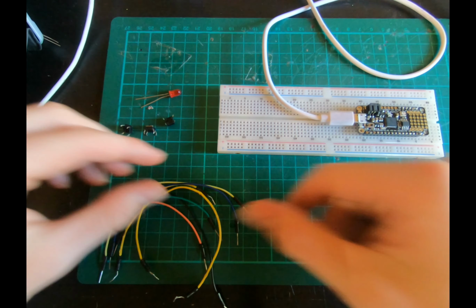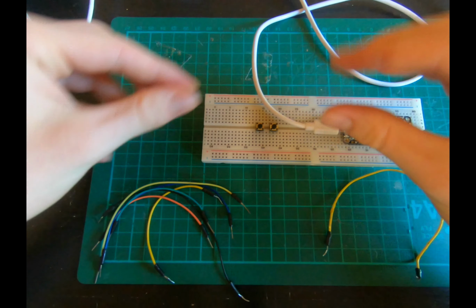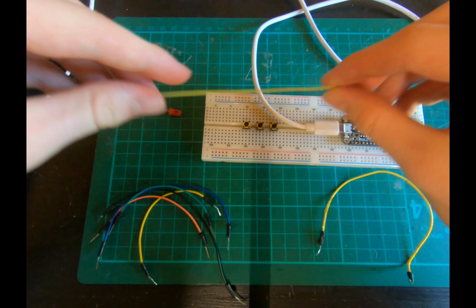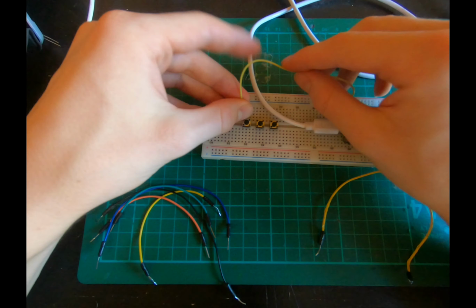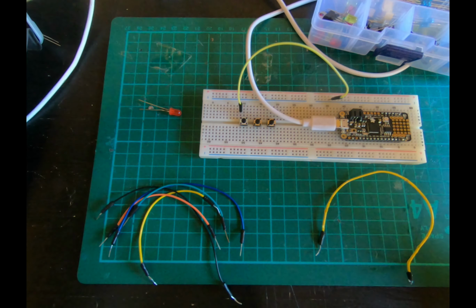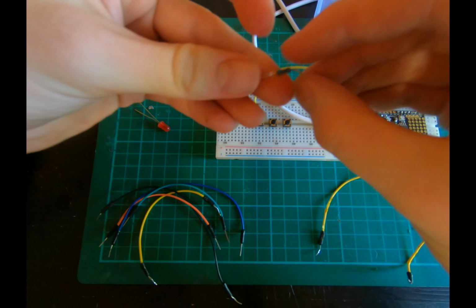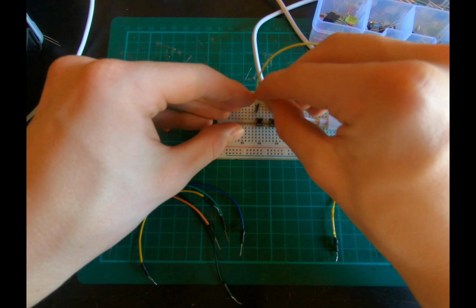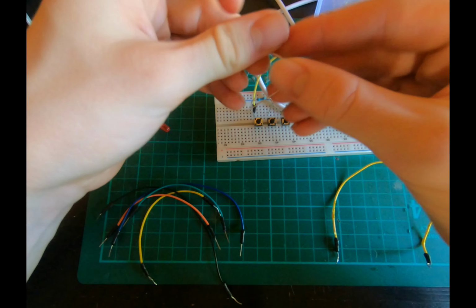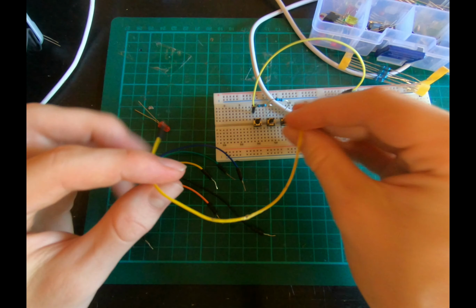So let's wire this up. What we're going to do, we're going to get our buttons, so let's just put them across here, and another one here. There we go. So we will want to connect these all to the ground. And if we get some resistors, let's get some resistors in here. So we want these going to each of the pins of the buttons. So this means that there will be a supply of electricity going through.